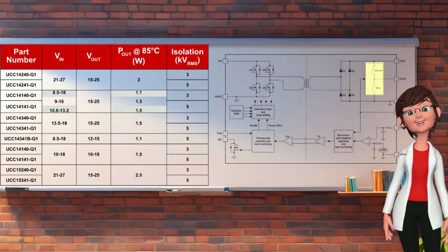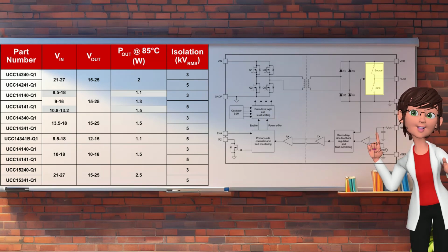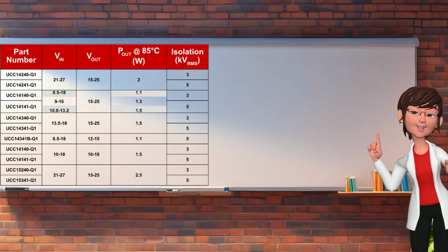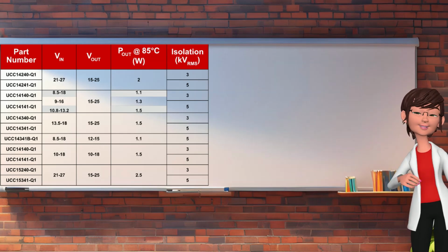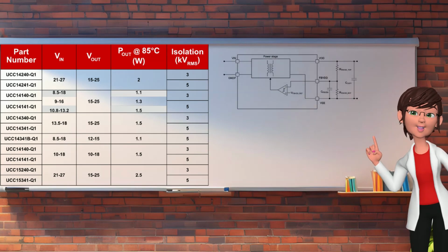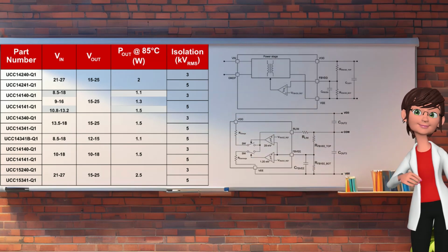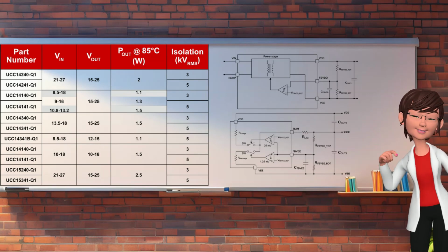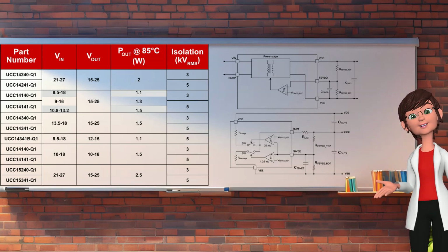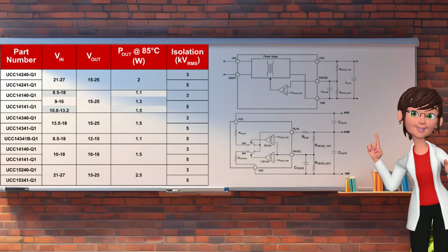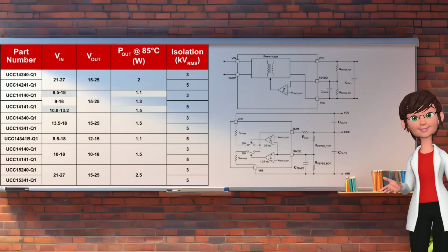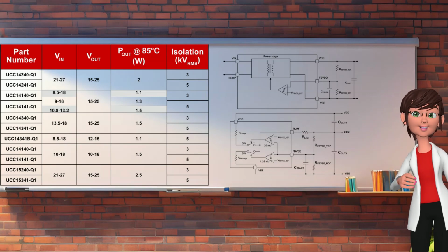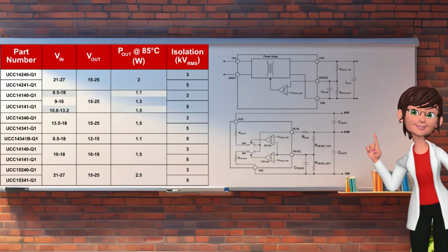So why do these isolated power modules have a source and sink LDO at the output? The reason is that the secondary side can be configured as a single-ended output or a dual-rail power supply. This allows you to easily create a negative voltage rail to ensure the FET is disabled. So depending on whether you choose to use traditional silicon, SiC, or GaN FETs, the right isolated power solution for your gate driver is right here.